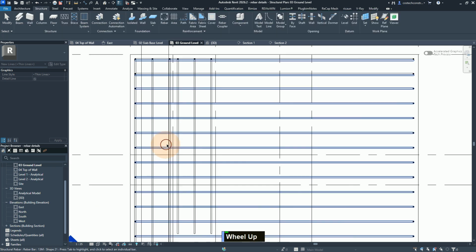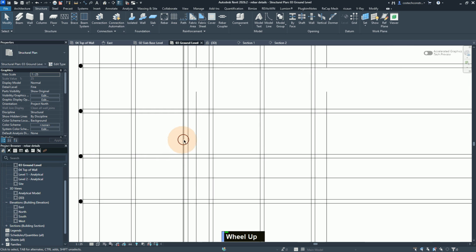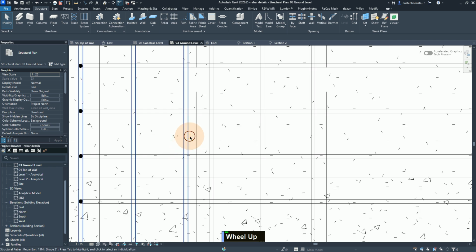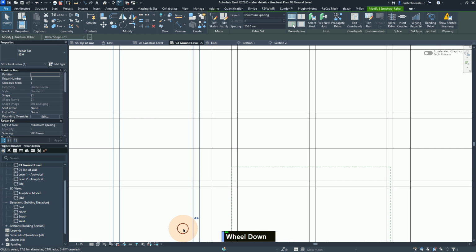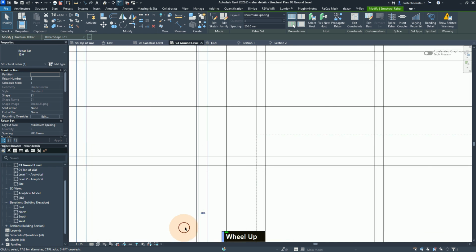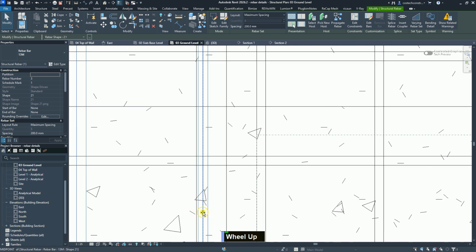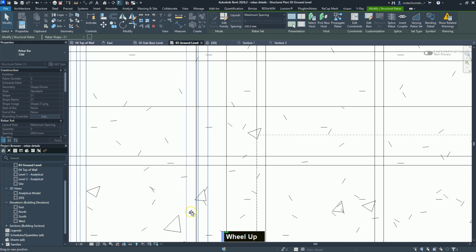we can now select. I will select on any rebar at this point. And if I zoom at here, we'll zoom. We can highlight it, and then we can place it somewhere where it snaps to the detail line here.